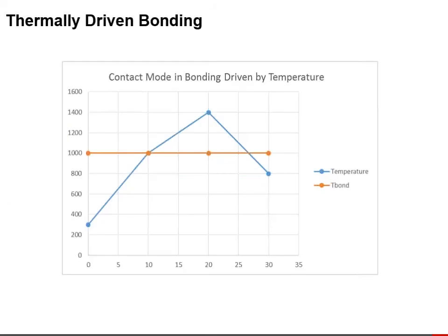And what it really means is, if we look at the case of contact mode and bonding, we'd have no glue condition here, so things could slide relative to one another. Then it would reach a certain threshold. They would then be glued together. And if you didn't have a debonding threshold, then those bodies would stay glued.